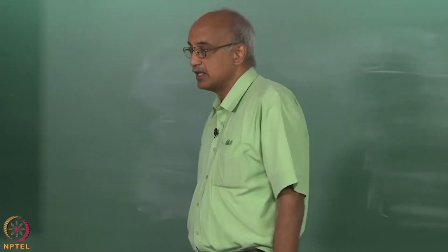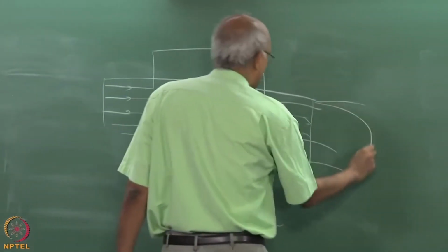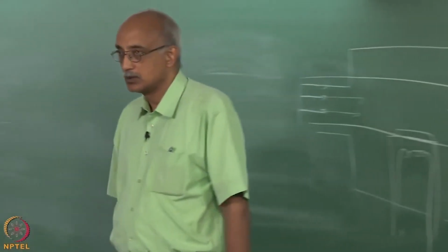Remember we said it is going to be laminar. So, in a tubular flow under laminar conditions, what kind of velocity profile would you get? Parabolic, right? So, the basic assumption in all of our transport modeling is that flow will enter as a plug flow and leave as a parabolic flow.